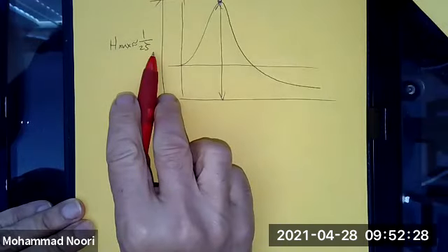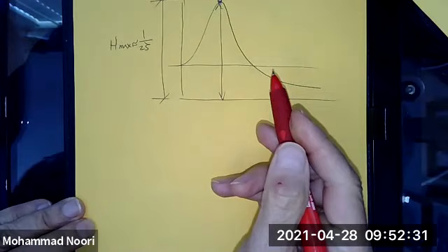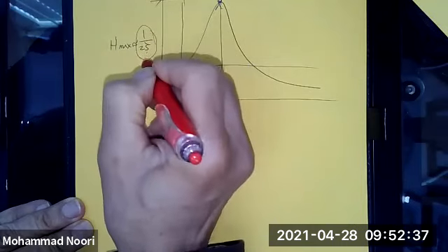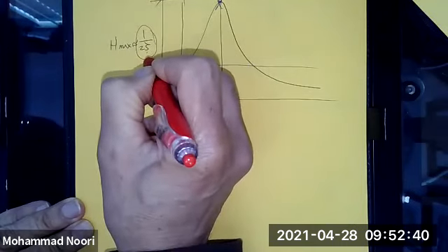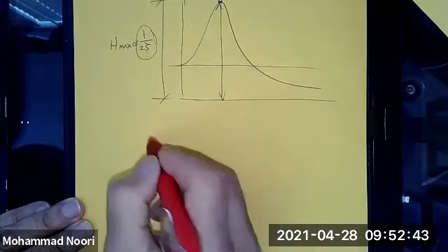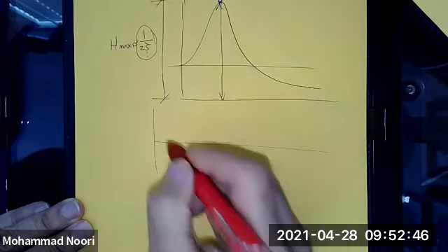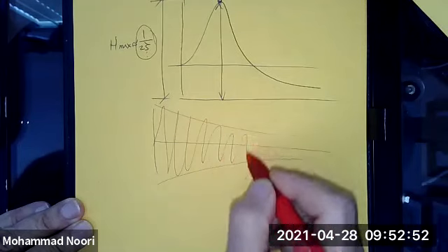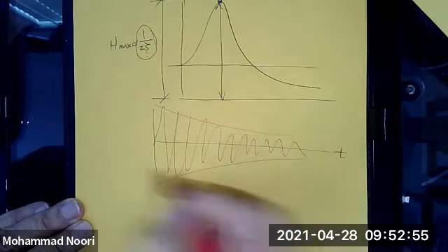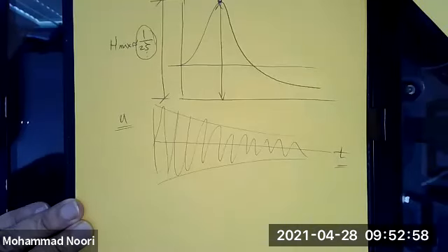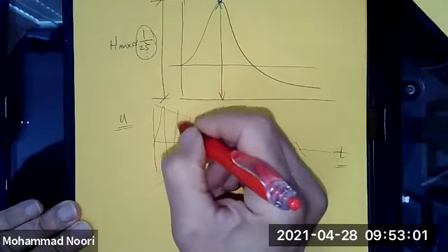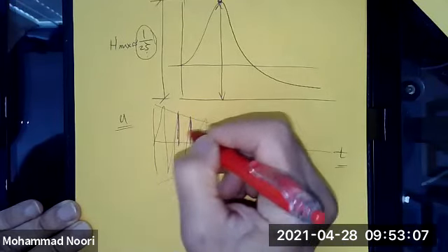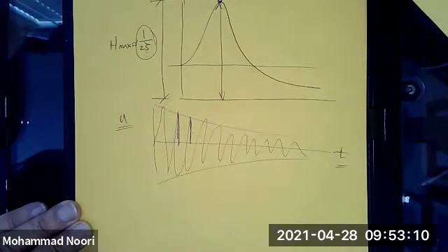What this is going to tell you: we just introduced a different way to find the damping ratio in the system, which is actually an easier way. You remember we introduced one way of finding the damping ratio using logarithmic decrement, by using the time response of a damped system. If you plot the time response, it is not that easy to measure two consecutive amplitudes and use a logarithmic decrement.